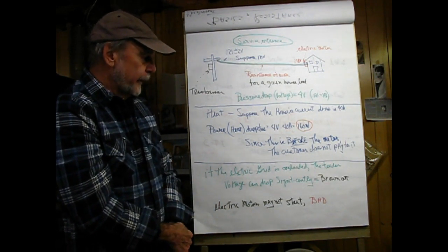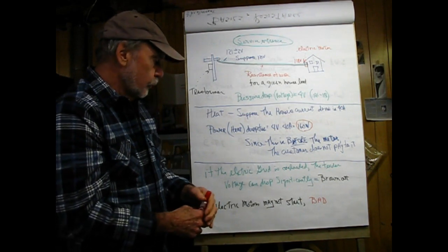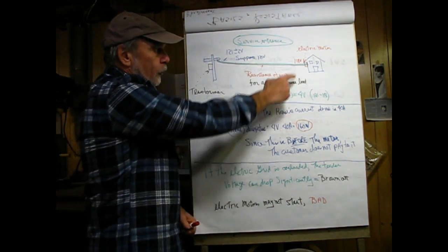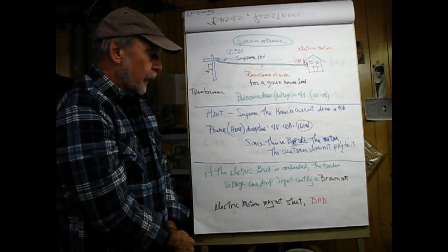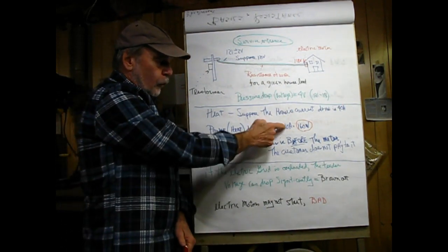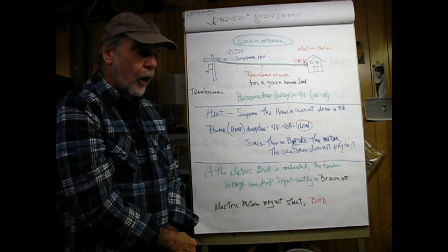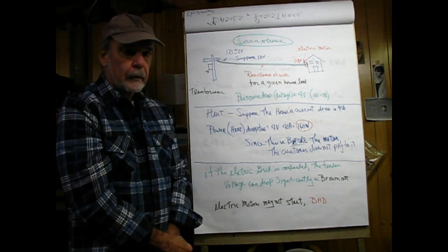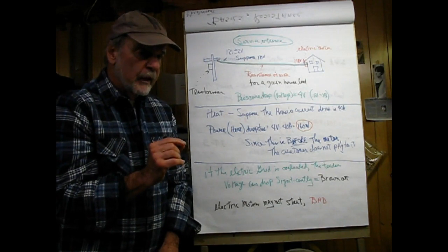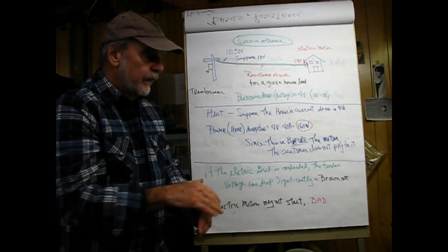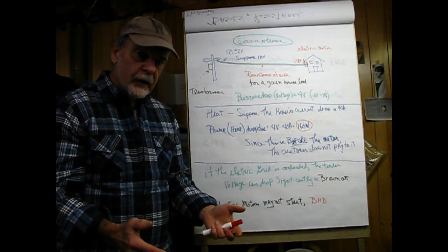Now, if we take a look and apply Ohm's law very quickly here, and we're going to get into the details later, so don't be concerned about it, we have a 4-volt drop in the service wire, and suppose our house is drawing 40 amperes. Power is equal to the product of voltage and current, and that turns out to be 160 watts lost in the service line. 160 watts, depending on the size of it, can be awfully, awfully hot. And if spread out over a large area, not so much.